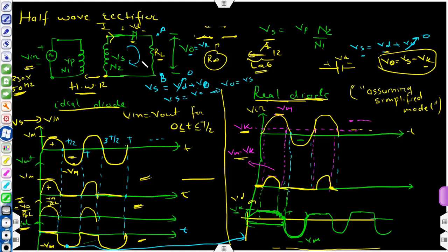So when you do this experiment of clipper or half wave rectifier, you can have one voltage analyzer at this point, Vd, across this Vd, and you can plot this. So you will observe that this kind of curve is coming. Okay, clear? The positive part which is showing zero drop will become 0.7, except for this small portion.